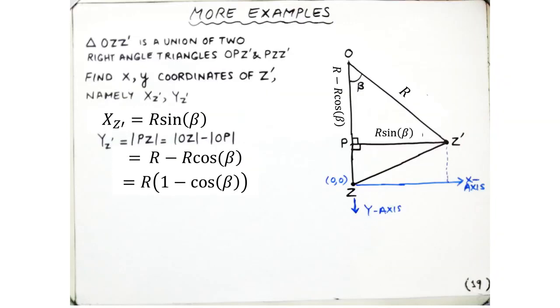We know that there is only one component of energy in this problem, that is the kinetic energy of the planet gear A. Again, a gentle reminder that we are not required to write the equation of motion of the sun or the ring gear, so their kinetic energies are ignored. And there are no elements contributing to the dissipation or the potential energy. Specifically, there is no potential energy in the system because the gear system is placed in the XY axis.